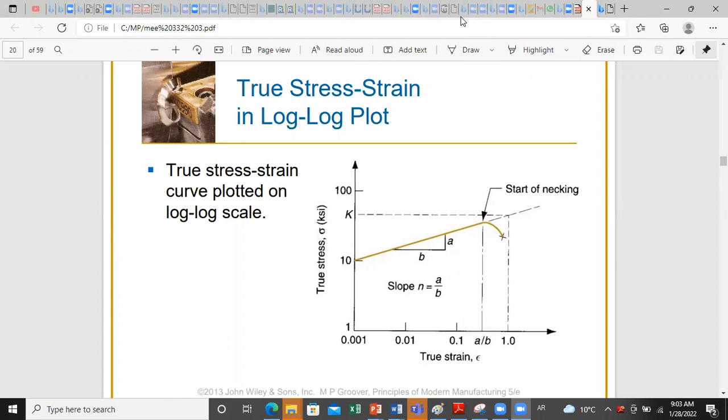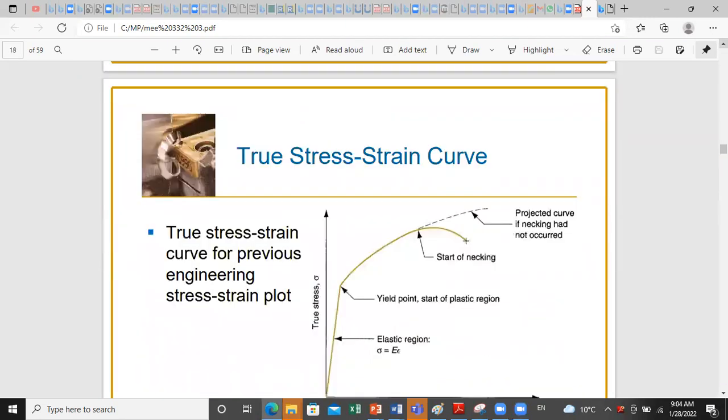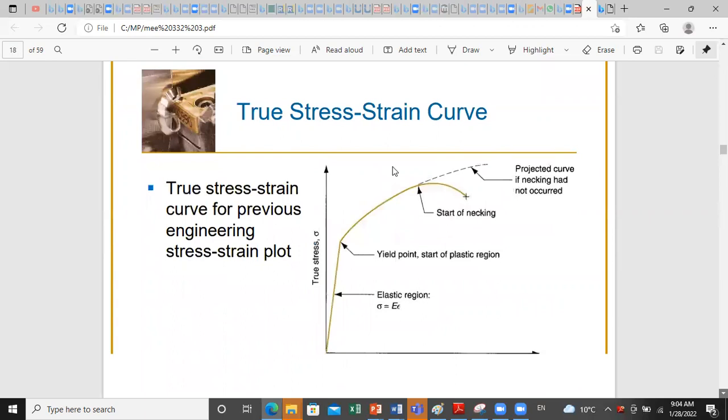Last time we introduced the concept of stress and strain and true and engineering graphs. And we were saying that the true graph will have more physical representation because it takes into consideration the actual reduction in area during the tensile test. And we said that each region is characterized by its own equations. So first, we divided the graph into three parts.